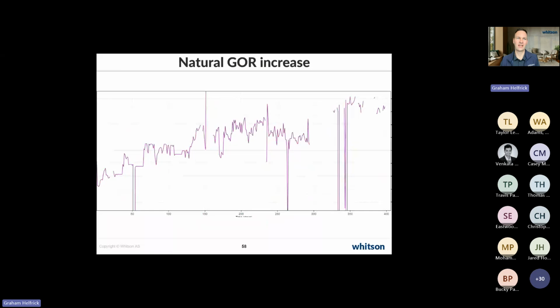Now, just to take the pressure off. How does this happen? How do people let over injecting occur? Well, it's because initially the GOR from the reservoir might be low. And when it's low, you need gas lift. But as the reservoir GOR naturally rises through the well's life, the need for that gas lift becomes less and less. And so if you haven't looked at the gas lift on your wells in a little while, it might be worth checking it out to see if it's even really needed anymore. Okay, it depends on the well, but especially if GORs are rising, you may need less gas lift.